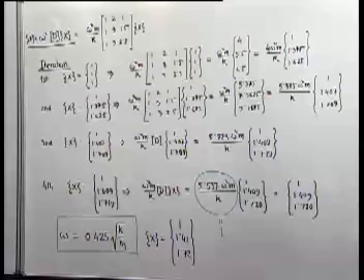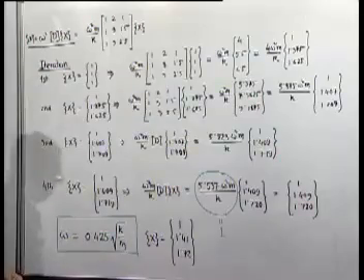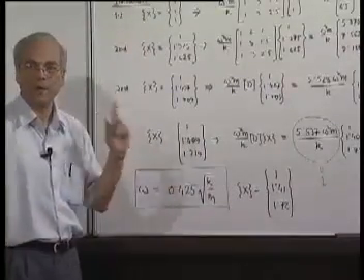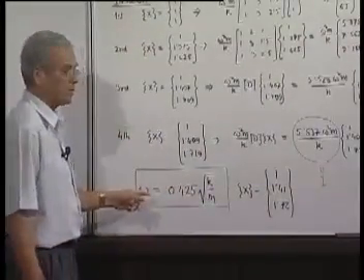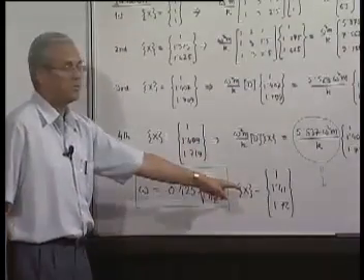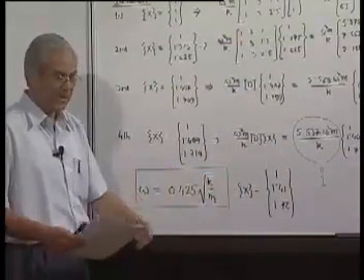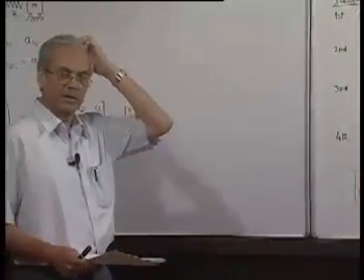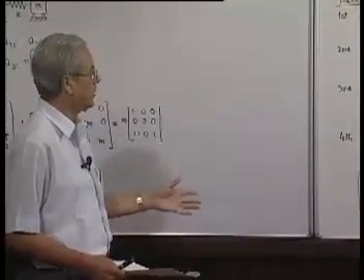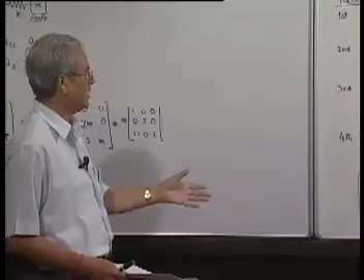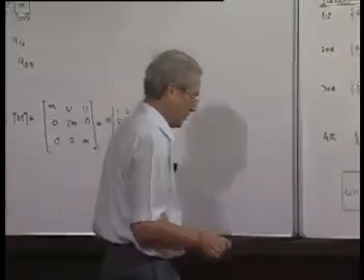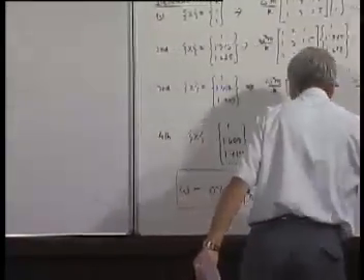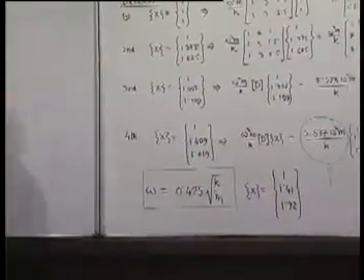But the question is that which mode is this? Now it can be proved, as I will be doing now, that this is nothing but the first mode or the fundamental natural frequency, and this is the first mode. Why is it converging always to the first mode? If that is the question we have to understand, then we will digress from the iteration procedure for a short while.